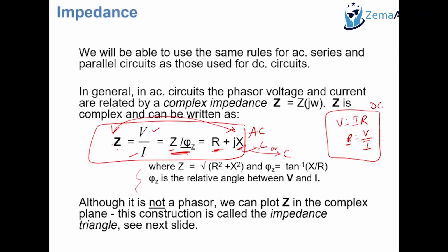What I would suggest is when you write phasors, if you're writing by hand, always use a bar at the top. Yeah, it's quite difficult to get that when you type things. But when you write a normal equation, say Z equals V by I, if they are phasors, just use that notation at the top. That indicates it's a phasor. If you don't, then it means it's not phasors, so there are no angles associated, in which case the whole thing might become wrong. If there are no angles indicated, then Z should not be Z, it should be R.